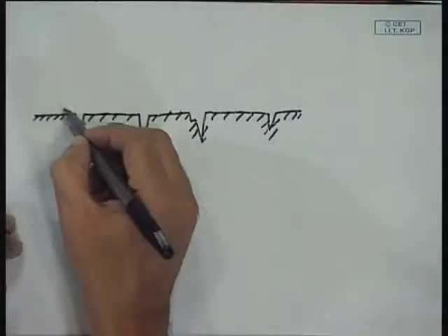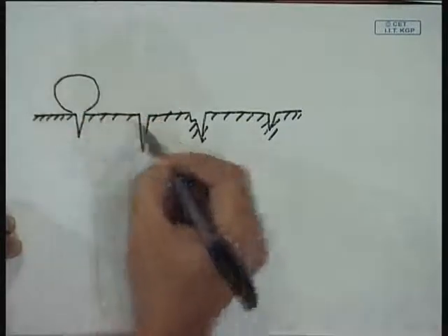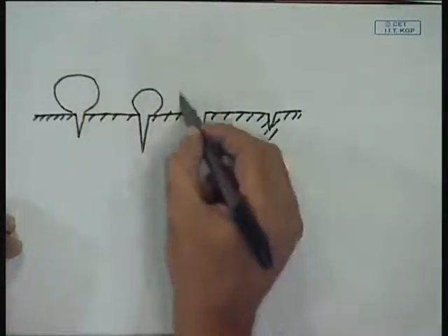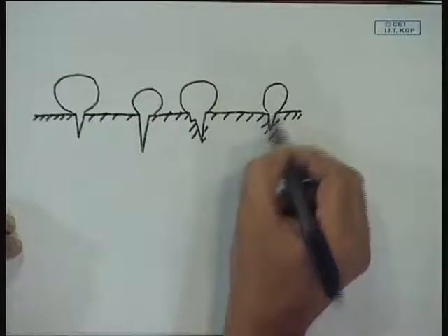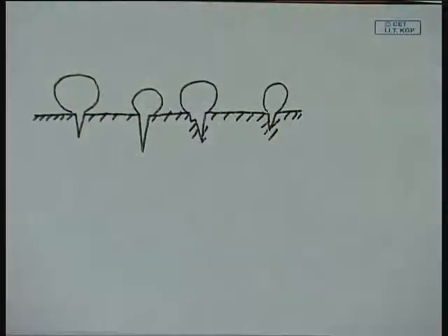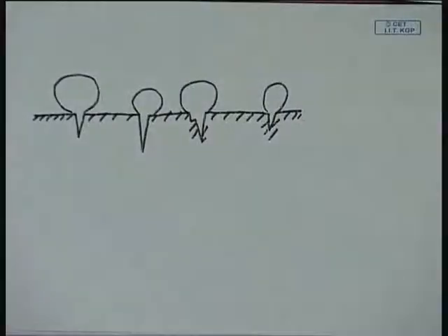On each of the sites we have some sort of a bubble. So, this is your state of isolated bubbles, or boiling due to isolated bubbles, and you can understand that this is due to heterogeneous nucleation. On the heater surface there are different cavities which have been activated.